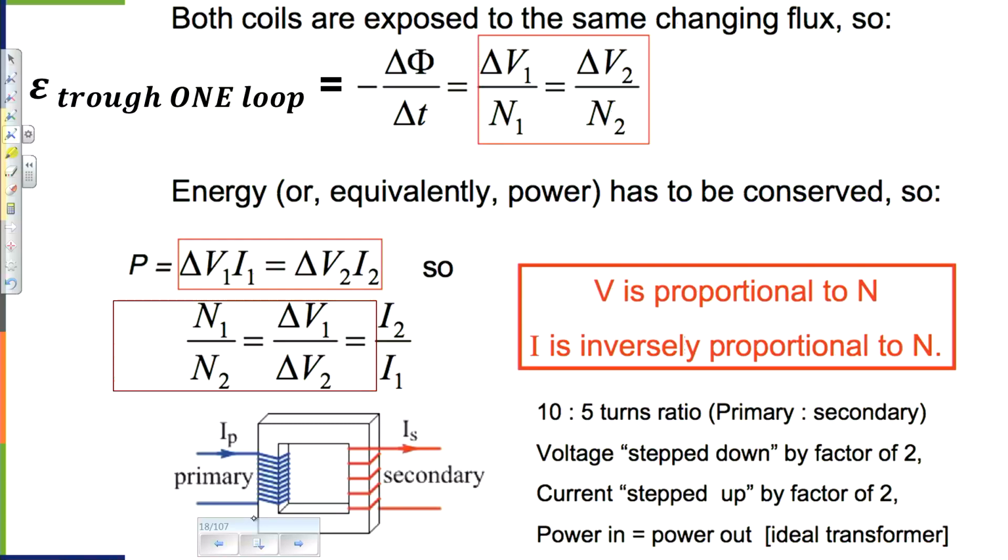Second relationship is basically a law of conservation of energy. Assuming there is no energy loss, the energy we pump every second into the first coil should be transferred to the second coil. And the energy, on average, technically those are supposed to be RMS, root mean square values, or maximum values, not instantaneous. But we get a second equation which relates electric current in two coils.